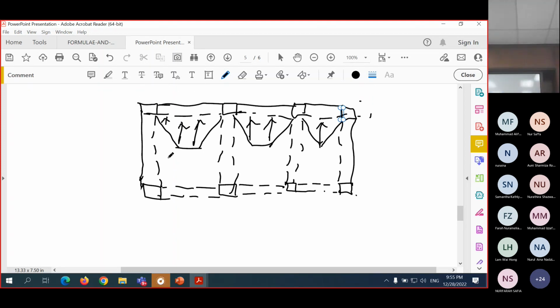So in the next stage, class, what you should be doing now is you finish your slab designing, then your beam. So you have to know the load acting on the slab that you have decided in terms of kilonewton per meter square. And then you need to know how the load is being distributed to the beam.